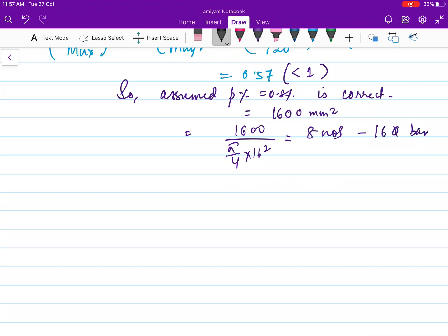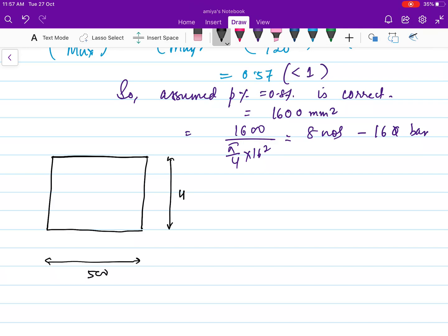Now this is your column, this is 500, this is 400. So you are going to provide 8, meaning let me provide 3 here, 3 at the bottom, 6, so 7 and 8. Okay, so 8 numbers of 16 dia bar I am providing, and we have to provide the ties also. So in the next video I will be designing as per IS 13920 the shear requirement.